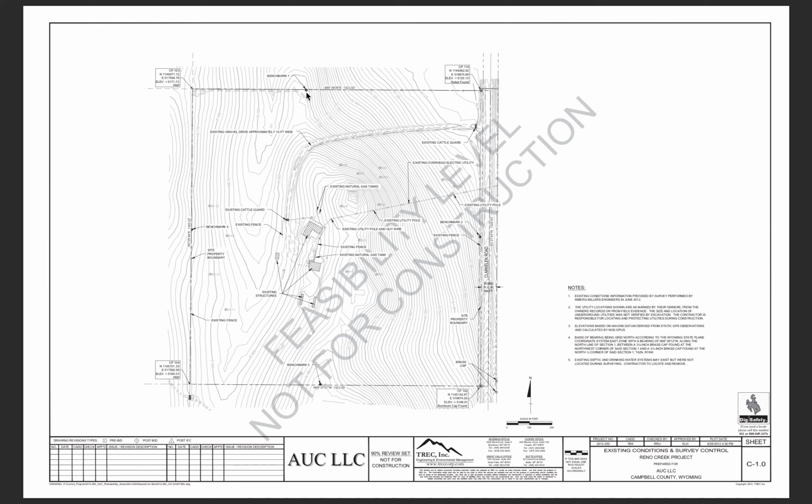So as a surveyor, I would come in, I would set up on those to get an elevation for myself, and then I would go about either setting or finding these corners, and note that this is a road, and we would note the right-of-way on it on these upcoming pages. So we set up on those benchmarks, and then we could note a cut or fill for the building site.